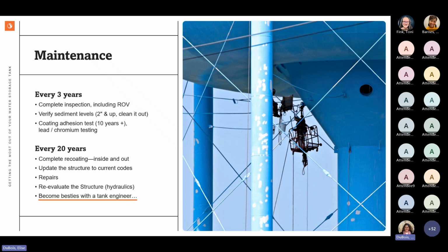However, depending on the shape of your tank, getting it clean to remove those sediment beds may require a diver or an ROV. Divers can clean all the shapes. ROVs and divers can clean and inspect your tank with the tank online. And failure to keep up with those inspections and cleanings will require the tank to be taken offline, and usually for costly reasons.